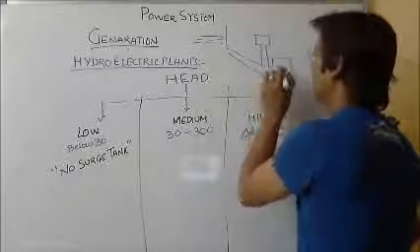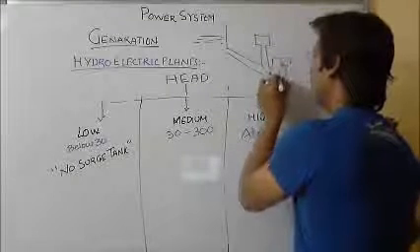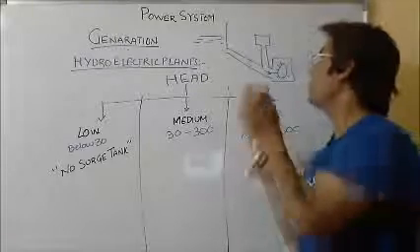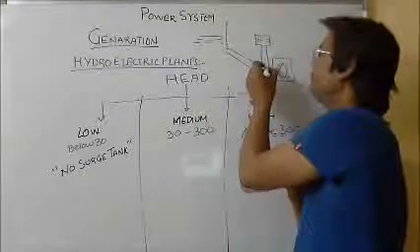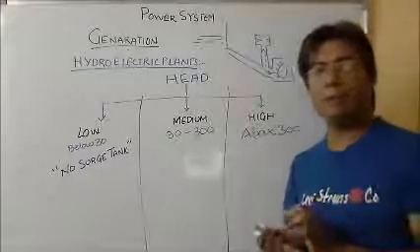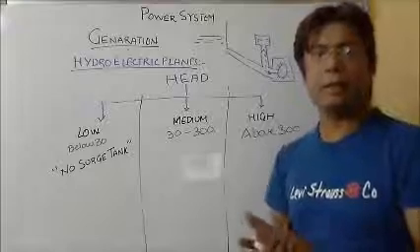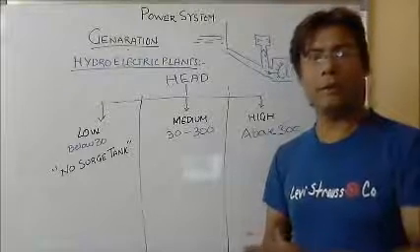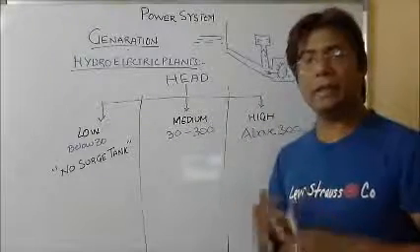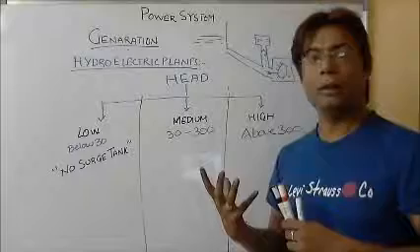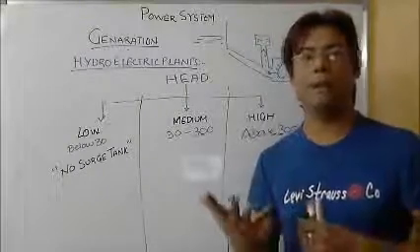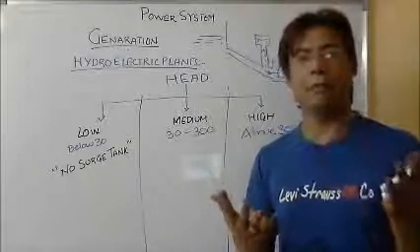What is the use of this surge tank? It is filled with water. See, during the load reduction period, when the load on the generator is suddenly thrown off, the load on the generator suddenly decreases, and it decreases the requirement of the load on the turbine part. As we have seen in electrical machines, when there is an increase in the load, it comes from the mechanical part.